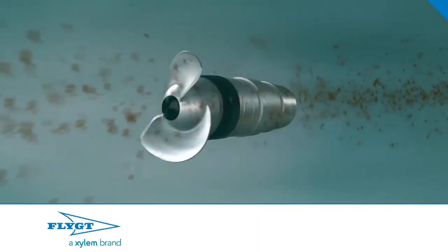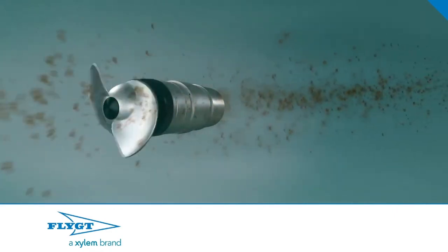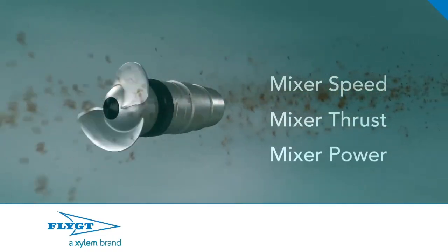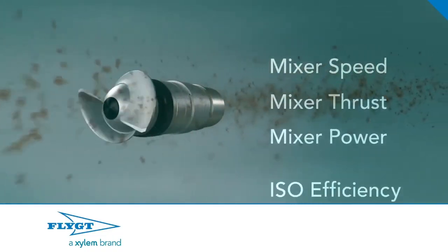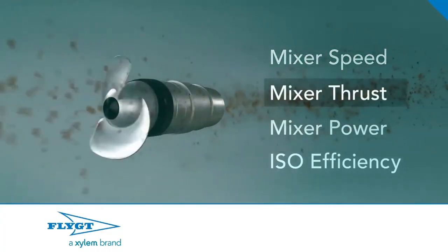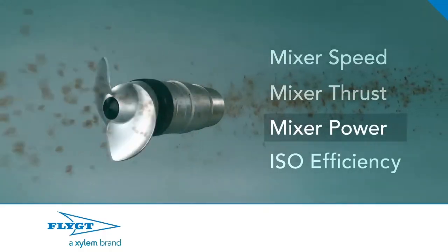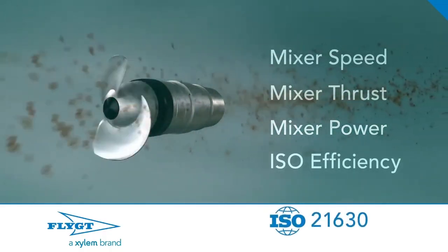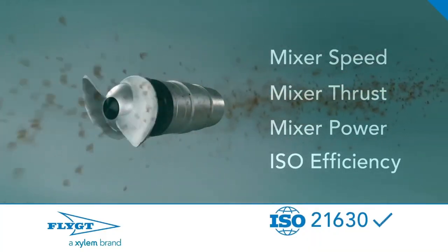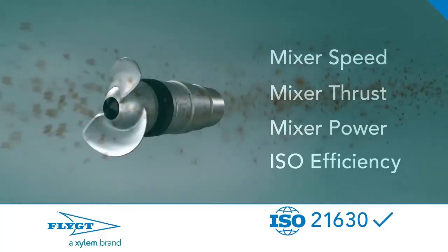To help determine the appropriate mixer, you should look at 3 key parameters: mixer speed, the thrust it is generating, and the power it is consuming to generate that thrust. This information tells you how hard the mixer is working, how efficiently it is delivering the needed thrust, and of course, what it is costing in energy consumption. Remember to look to the international standard, ISO 21630, for unbiased thrust comparisons between mixers. Never settle for rules of thumb or unsubstantiated claims.